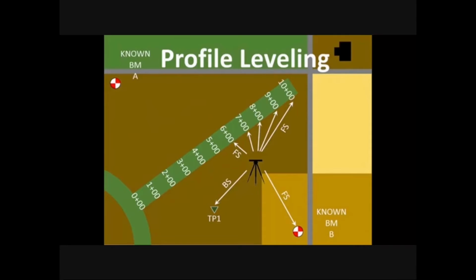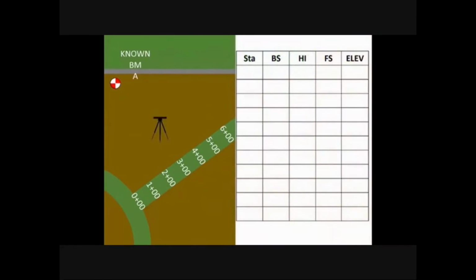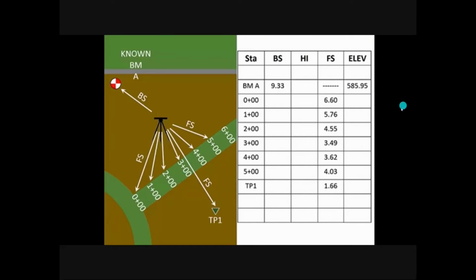Let's wade deeper into the water and explore proper note keeping and computations for profile leveling. So how do we compute in profile leveling? The first step is to know the elevation value of each benchmark. Knowing the elevation values of each benchmark is a common practice as civil engineers.